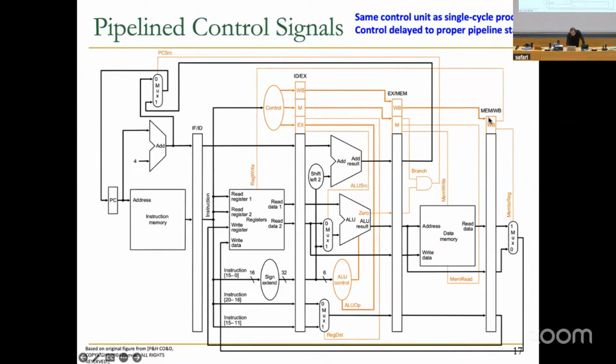It's connected to this pipeline register over here, which is the write-back pipeline register, which says that the instruction in the write-back stage is supposed to write to the register file, because that control unit, when it decoded the instruction 3 cycles ago, set that signal appropriately, hopefully, because it's an instruction that tries to write a register. So we're going to connect that control signal in that register into the reg-write signal of the register file. Make sense?